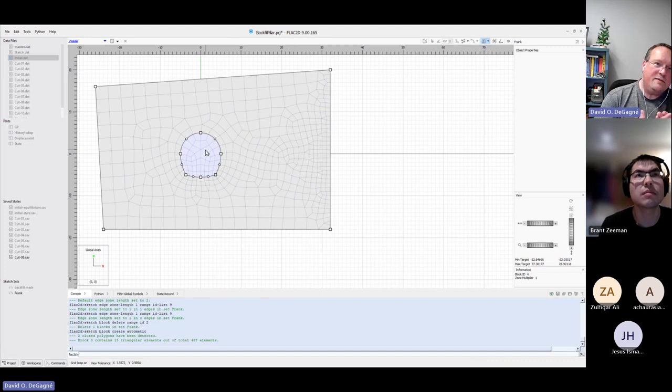Okay, so have you ever seen a 2D analysis where in 3D, if you've got a tunnel and you're excavating along a drift or a tunnel, you can kind of put a measurement point in at some point and then continue to mine. And if you're monitoring the vertical displacement at that point, what you'll see is this gradual closing: the tunnel roof will start to close further away from the face of the tunnel. And so it's sort of like that.